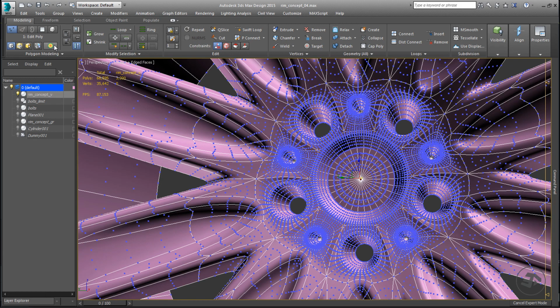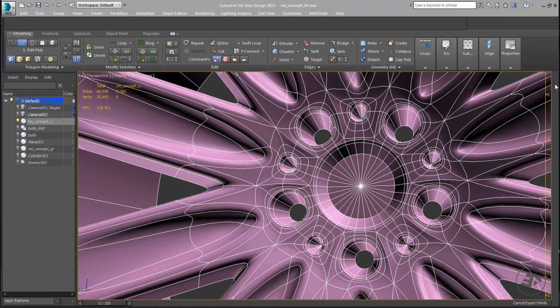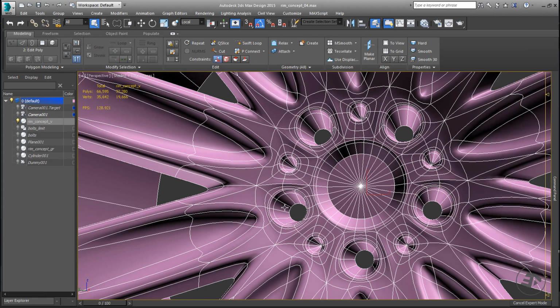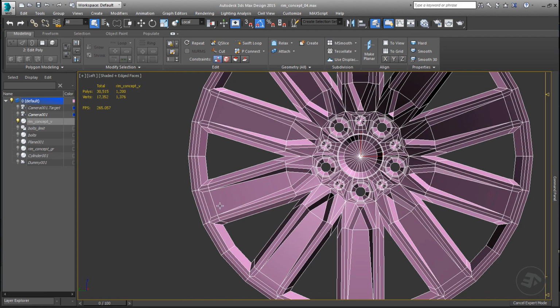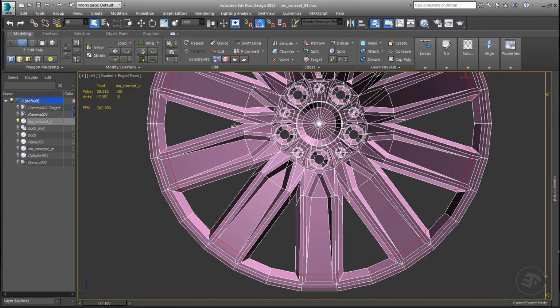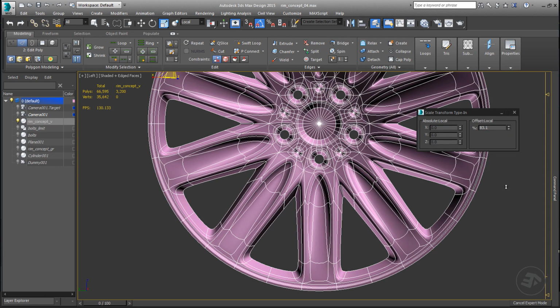The following is the final editing we shall do in this chapter. I am going to do it on a new Edit Poly modifier. There are other key points that control the geometry. For instance, the selected edges, which can control the width of the spokes.